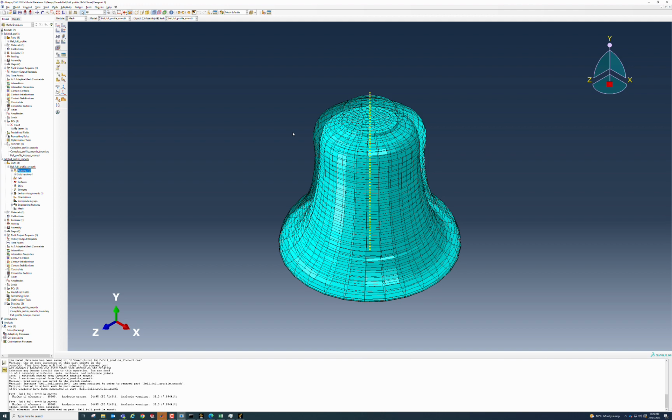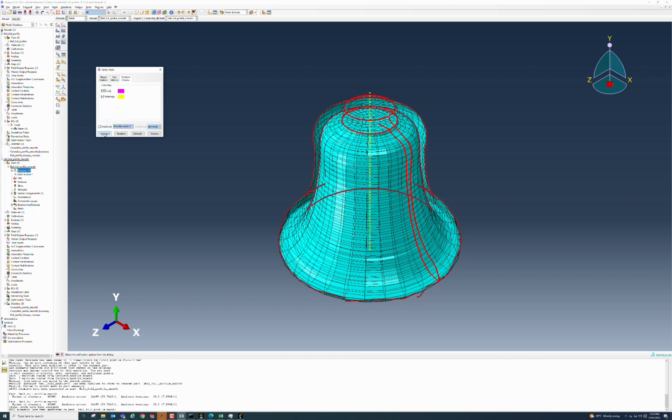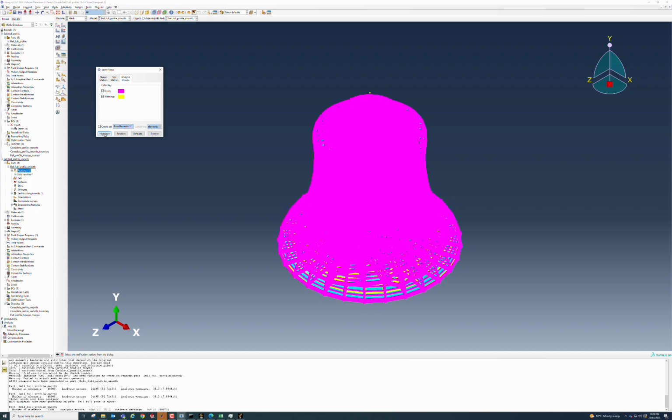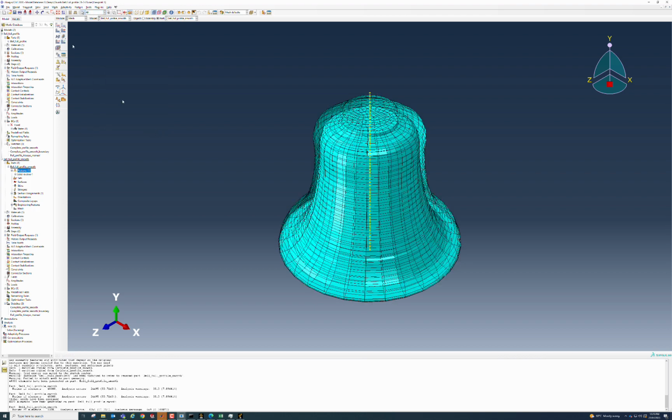There are indeed applications such as HyperWorks meshing just for the job of building meshes. Abaqus meshing is okay, but not one of the more powerful industry standard meshing capabilities. We still have these mesh problems with these hexahedral elements, even with a coarser mesh. And instead of the coarse mesh, we can actually then have a look at changing the nature of the mesh elements.